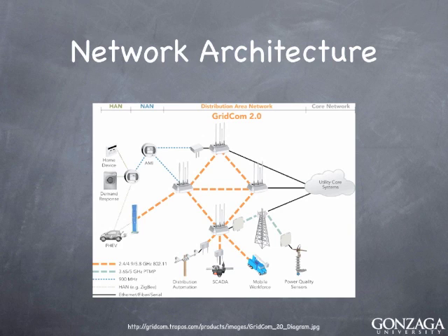And then there's the meter that's represented by AMI. AMI is an acronym that stands for Advanced Metering Infrastructure. In this case, it shows that it's a 900 megahertz system. There are ANSI protocols that typically metering manufacturers will use. Those, again, are standard protocols. But because of the security concerns, most of it is encrypted in such a way that really you don't have interoperability of vendor meters.